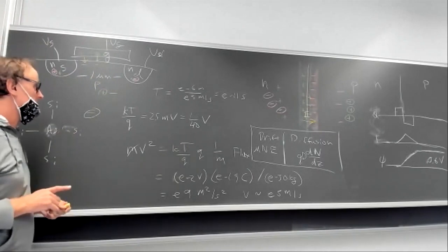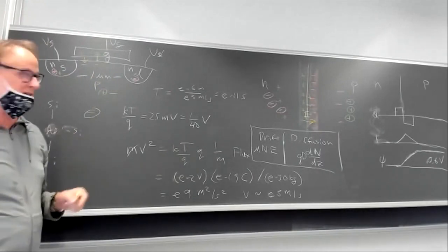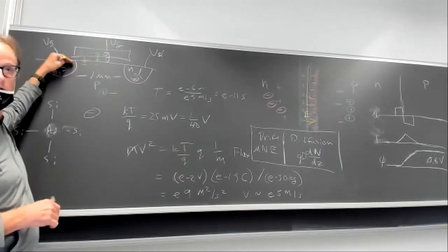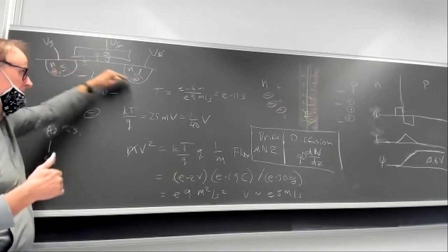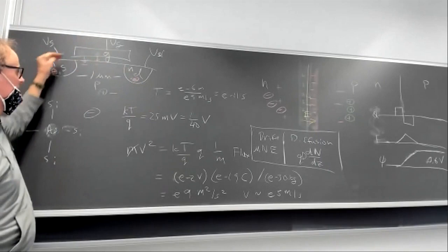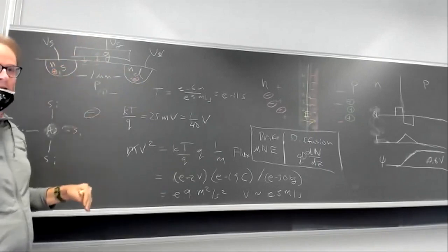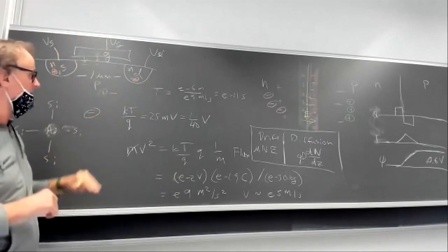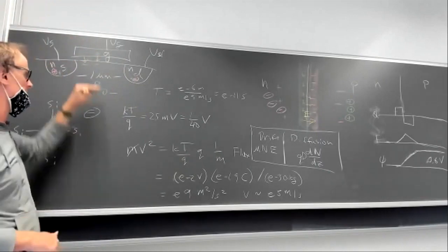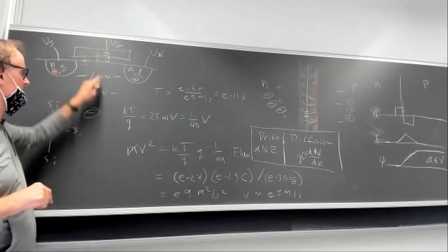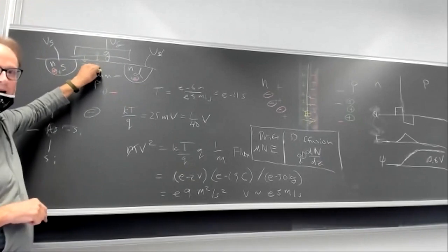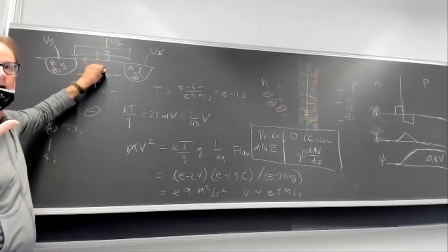But then, actually what's happening at that point is vapor starting to rush in from the source end. It's easier to rush from the source because the potential barrier is lower, right? Usually the drain's at a high voltage, so there's a huge potential barrier. So at the source, things are starting to rush in exponentially, just like vapor would start to go over the dam. The process is exponential because of the way the energy is distributed, but it's still a tiny fraction of this fixed charge. It's still dominated by these fixed ions. The charge density here is just these fixed ions.